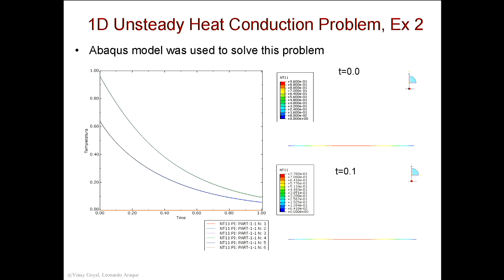Okay. In fact, in this particular problem, if I had continued, and I did this on purpose, if I had continued this time step of 0.1, although at the beginning it kind of looked right, the lesson learned that I'm trying to give you here, I use explicit, remember? Explicit integration. In this particular example, if I continue marching the solution, it will have gone unstable. Physically, non-physical.